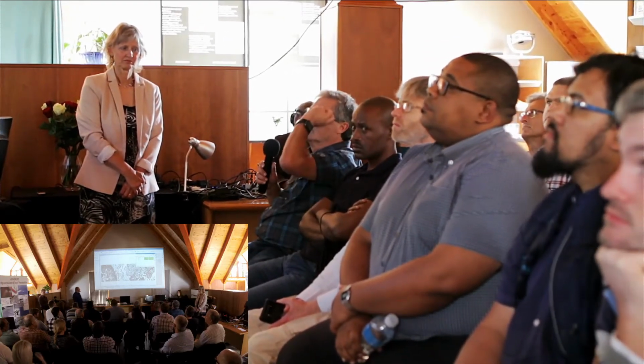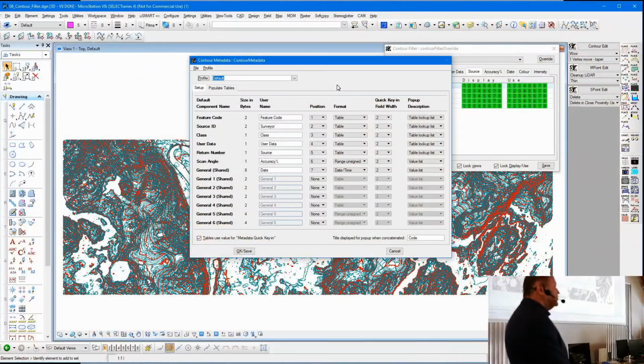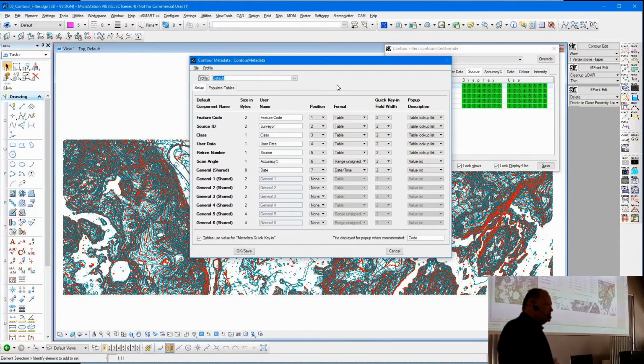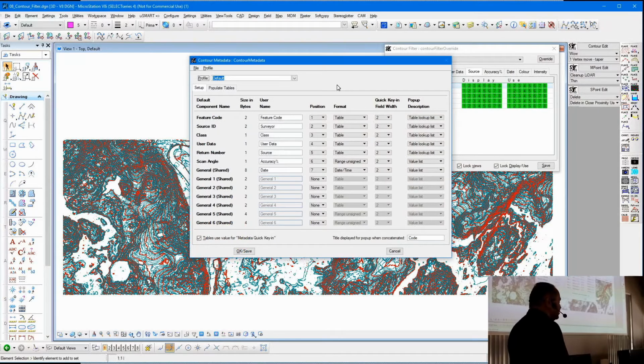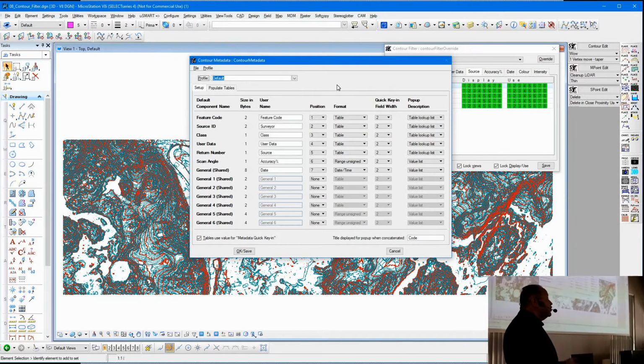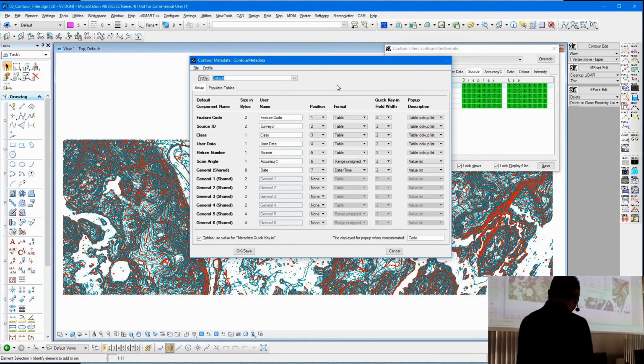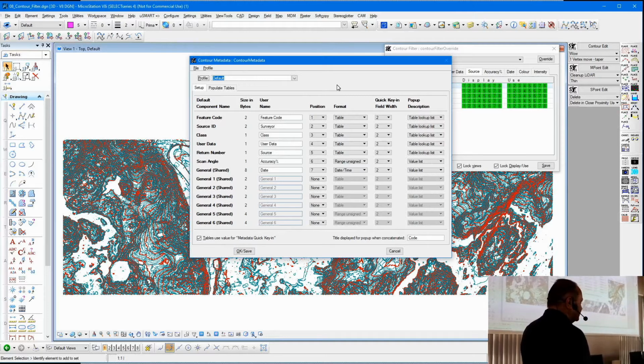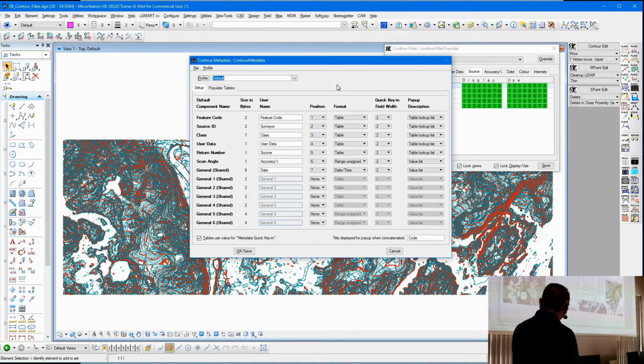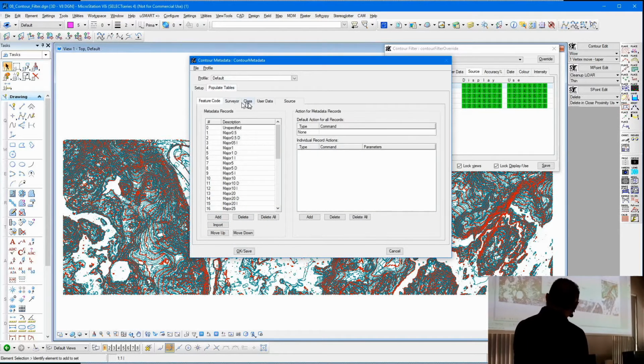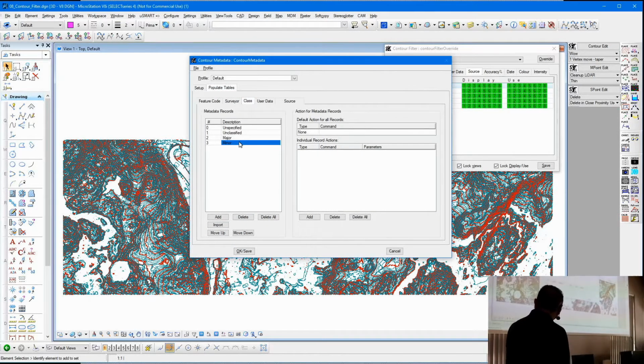Yeah. So whatever you decide those labels are, let's just go to the configuration and show. There are certain predefined classes in the LAS standard, which is an international standard, okay? And so the typical one to use would be class. But now we haven't catered for what you said. So we'd go to the populate tables, go to class, and say, okay, add this particular class.